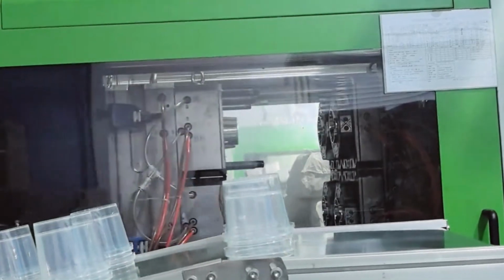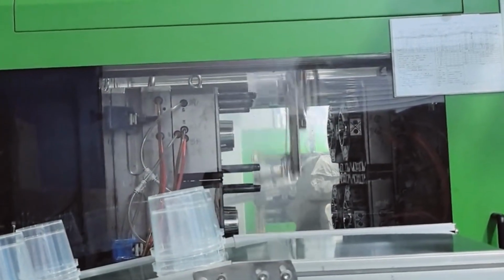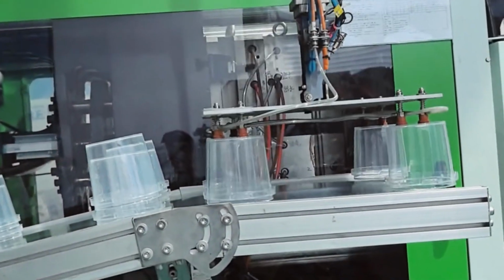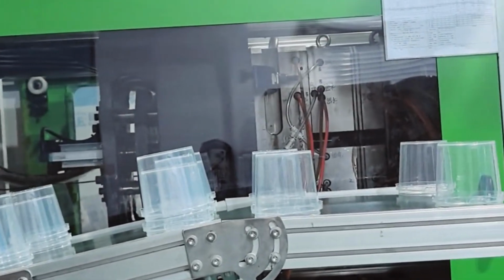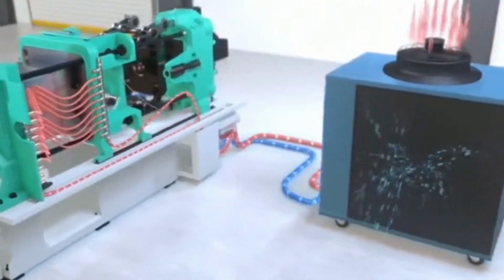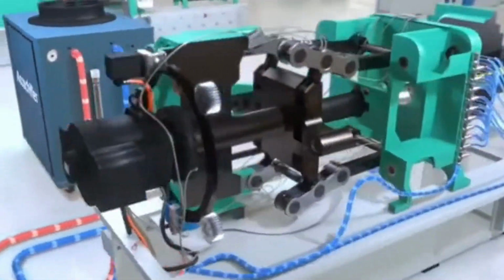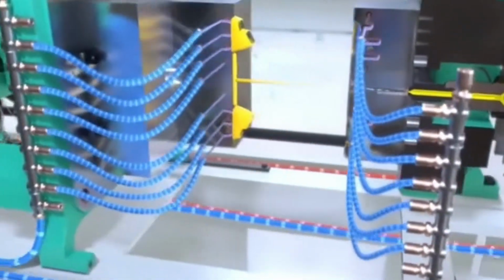Transparent products have higher requirements for the cooling system. The layout of the cooling pipes should be reasonable and should be as close as possible to the cavity surface to ensure that the plastic melt can be cooled quickly and evenly. For example, shape-following cooling, in which the shape of the cooling pipes matches the shape of the product, can effectively improve the cooling efficiency and reduce the residual stresses inside the product. A reasonable cooling system can prevent the product from deformation and excessive internal stress due to uneven cooling, thus ensuring the transparency and dimensional accuracy of the product.